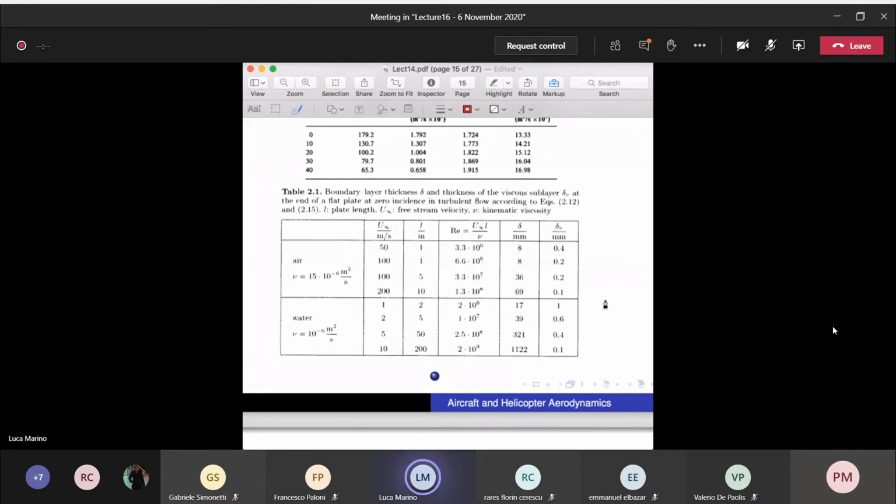I mean with the splitting, not the two effects, I said effect, it is wrong. We can split the two scales. So we can split what is going to happen in the X direction from what is going to happen in the Y direction. This number says that our boundary layer thickness will be of the order of 10 millimeters.